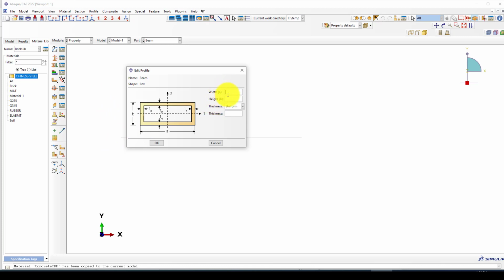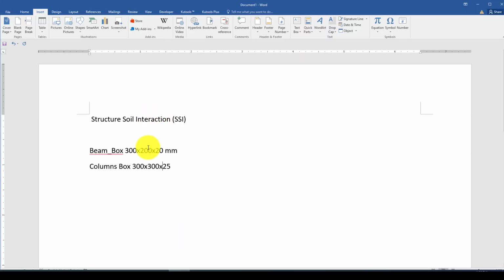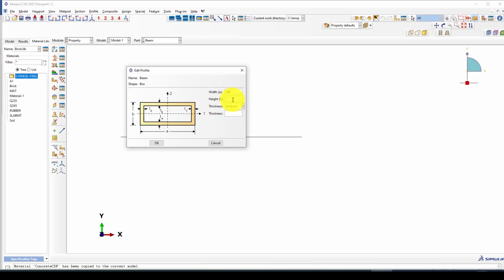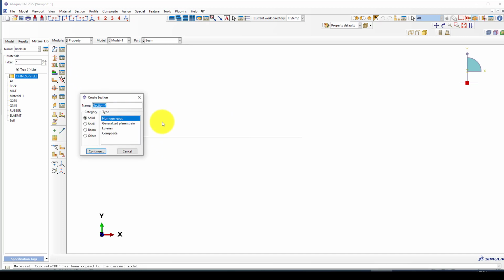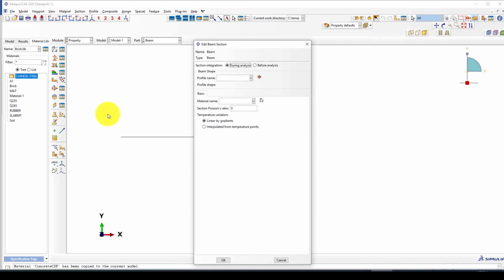The beam is the A, which is this one is 200 and 200, and the height is 300, and the thickness is 20 millimeter. So now we finished. We're going to create called beam using beam element here and selecting beam. The material is steel 345.